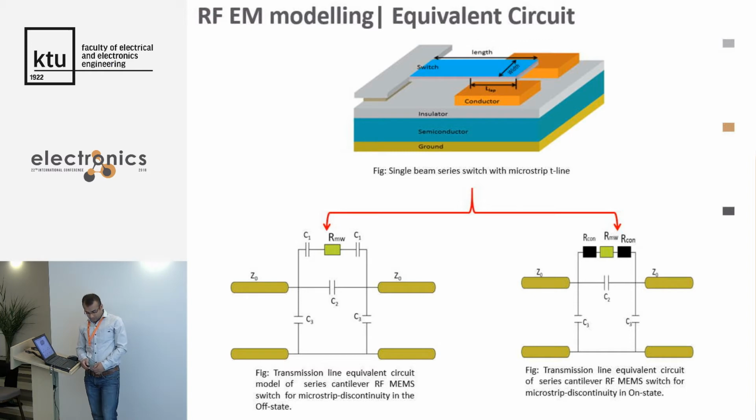So this is the actual device. This device is made with aluminum, and the actuation is with the piezoelectric principle. That's why we need around 2 volts or 1.5 volts to get the actuation, with a contact force of 350 micronewton, which is good enough for RF MEMS switches.